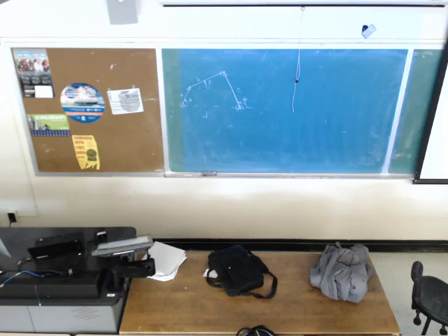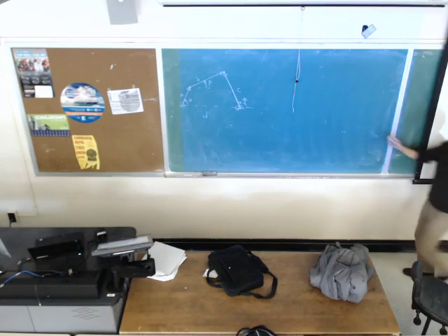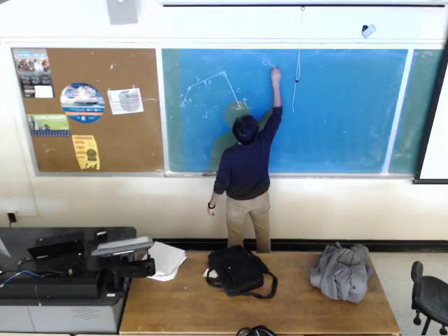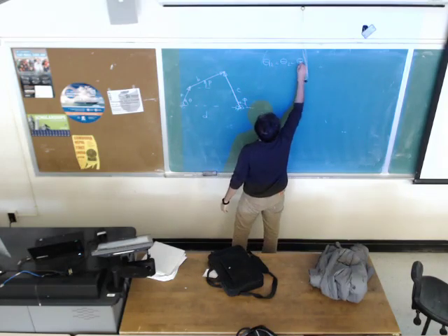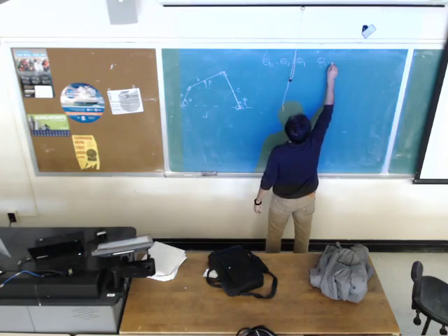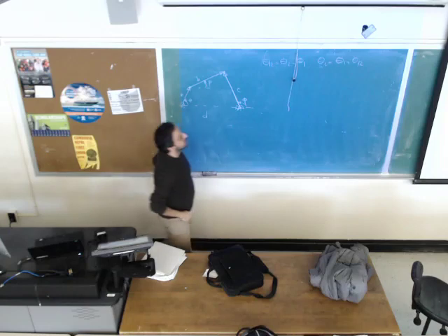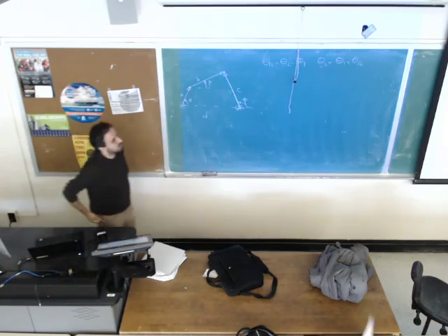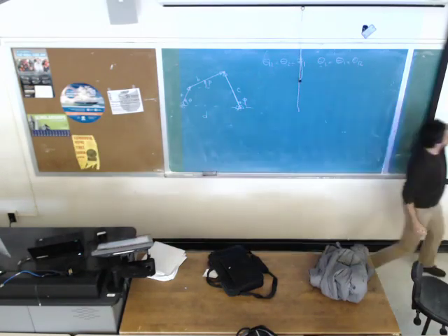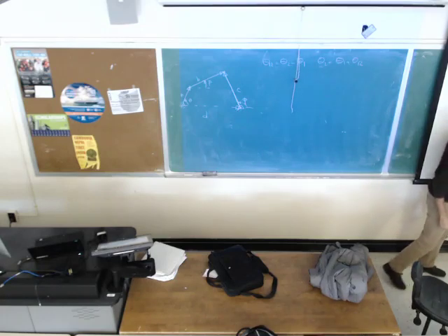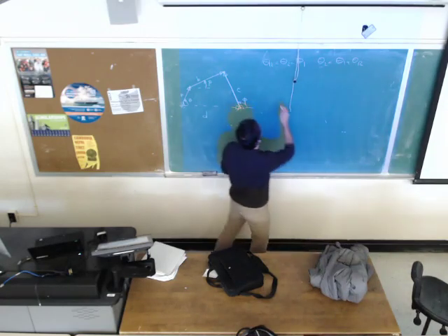So the first 2 equations are for the first precision point, I don't touch them. But for the second one, I have theta 2, and I'm writing theta 2 using this equation. Theta 1,2 is theta 2 minus theta 1, so theta 2 is going to be theta 1 plus theta 1,2. So for the angles theta, beta, and phi, I'm doing this.